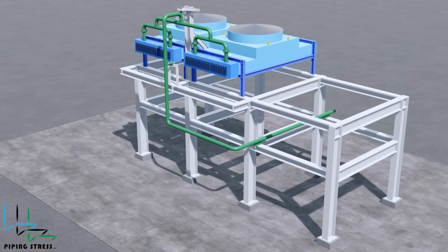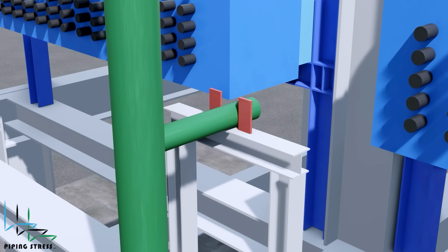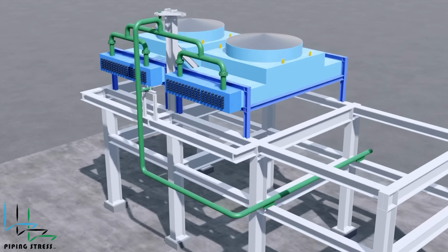Examining the pipe supports on the inlet piping reveals that the supporting principle is to liken the piping to the temperature behavior of the air cooler. The trunnion elevation is the same elevation as the air cooler support. This will help the piping to behave at operating conditions with the air cooler.